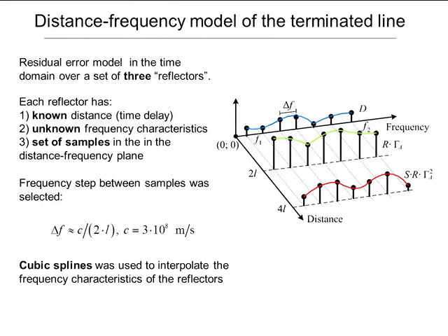And here we see the distance frequency model for measurement of the residual using the line and the short. You can distinguish the 3 components at the 3 different delays. But in general, they have unknown frequency properties. So it's necessary to determine the frequency response of each reflection.